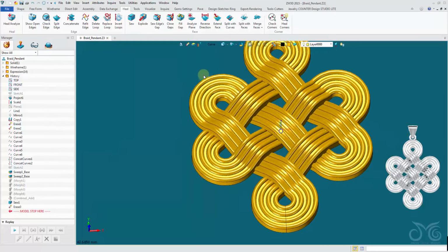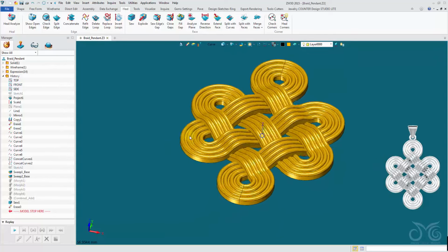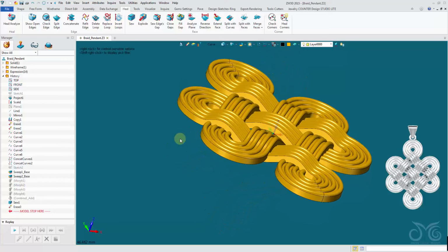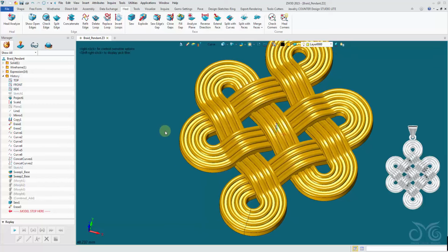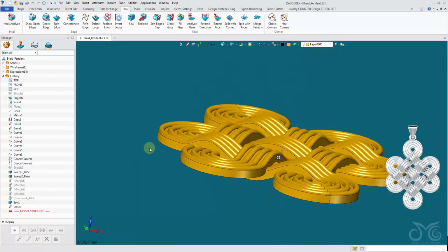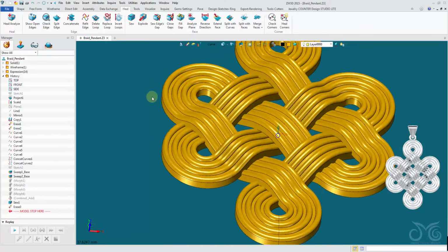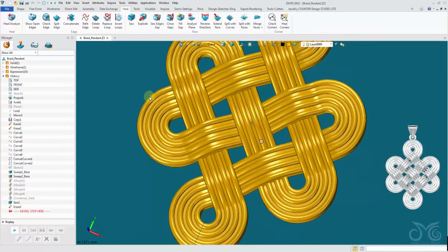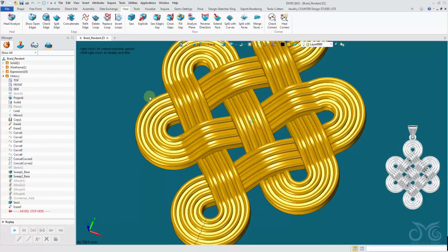Okay, now the advantage of this method using our curves instead of the morph command is that it is a bit more reliable. Since we are more specific, instead of picking points like in the morph command, we've been more exact with our pick points because we're using the curves. There are two methods there, and they both come with their own advantages.